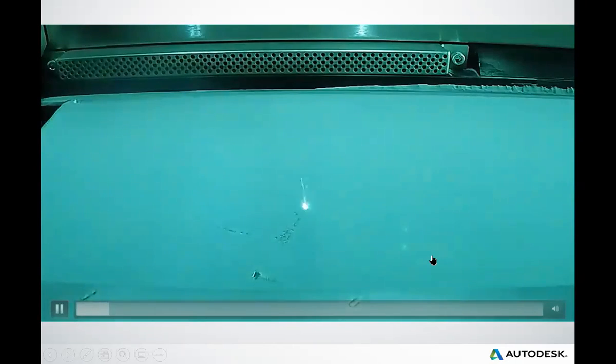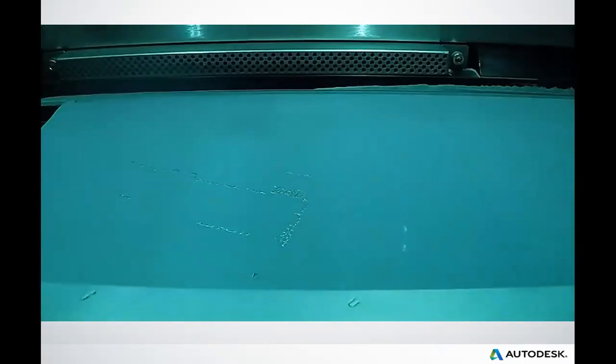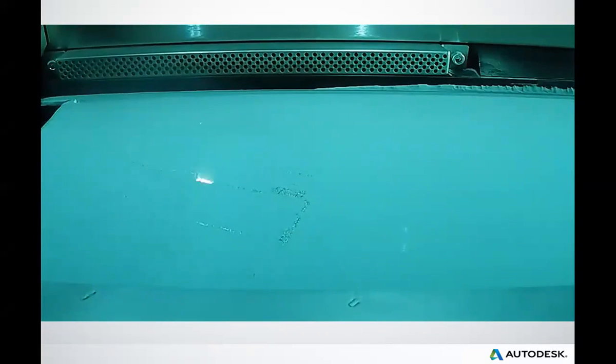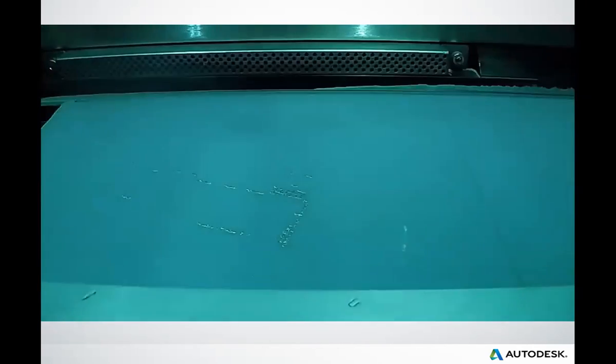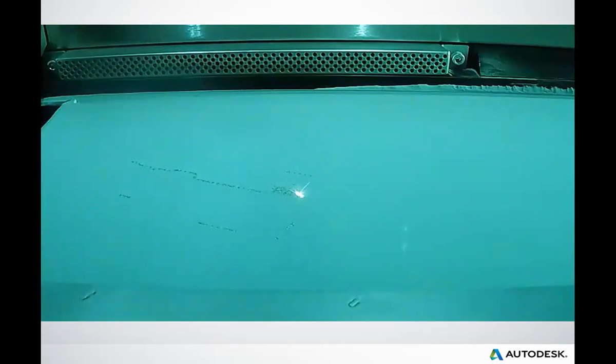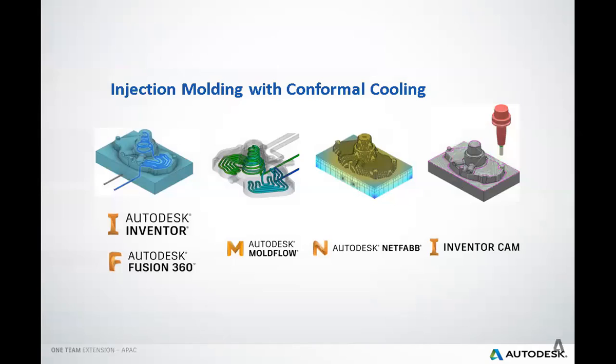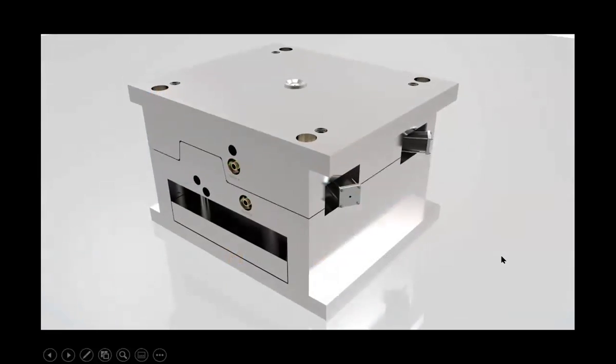And this one we show on the real machine doing the SLM technique. The roller will roll the powder in the bed, and then the laser shoots and melts the powder to combine with the previous layer. And the last one, Inventor: we have the CAM, and Fusion 360 also has CAM. If you want to do CAM, or computer-aided manufacturing, both Inventor and Fusion 360 can do it. But today, I will present the Inventor CAM.